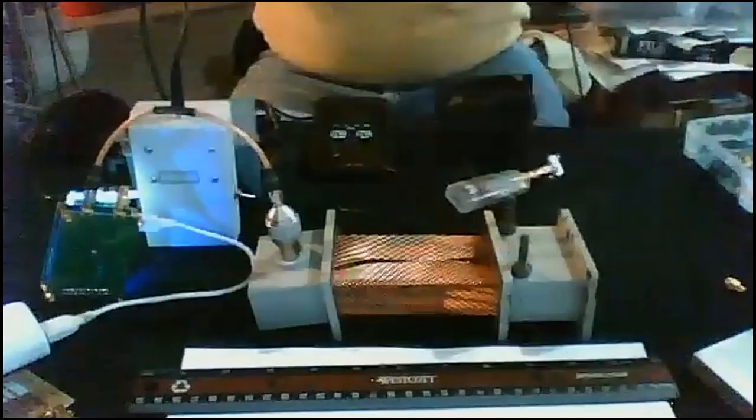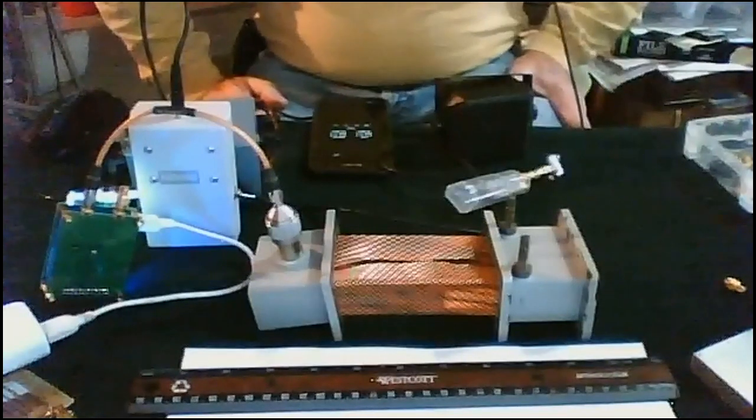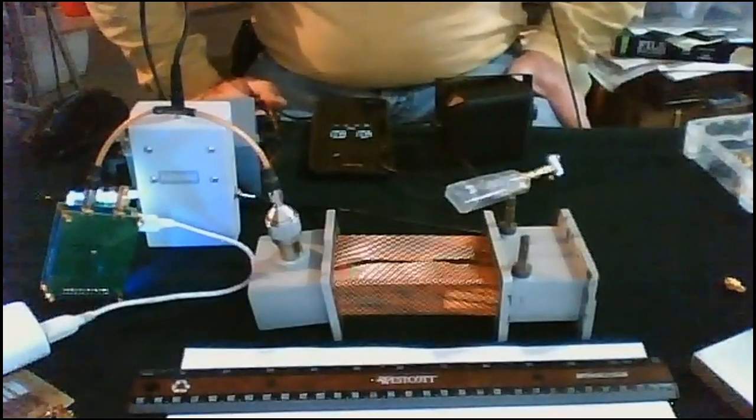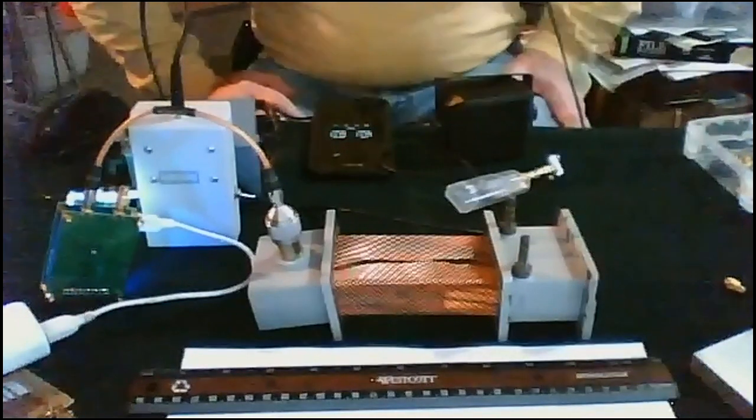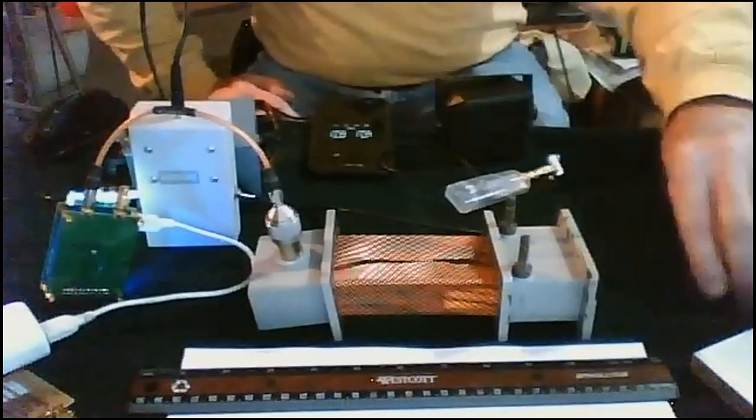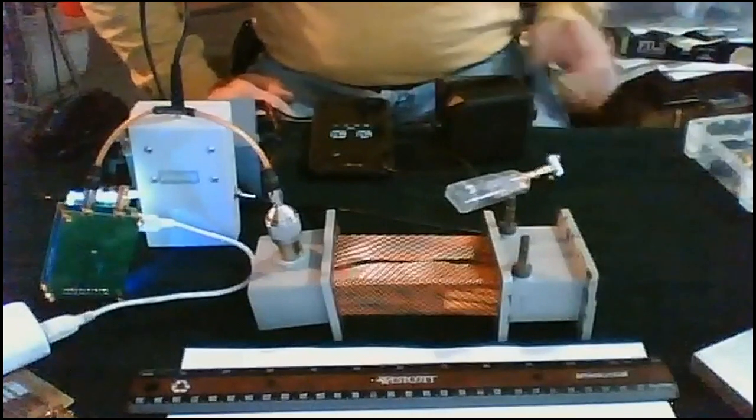So Paul, based on that question, what does your gut tell you if there were a dielectric to be introduced? What effect would it have on your results? It would shorten the wavelength because it slows the wave down. And using this methodology, you could actually chart to see how much quantitatively. Right, and you'd actually do it at the frequency of interest rather than at 1 megahertz where the manufacturers do it.